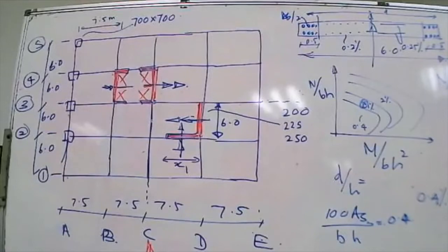They are useless calculations. Do a simple model where you will understand the exact behavior. And then if you want a very accurate result, allow it to a 3-dimensional computer program like ETABS. Because ETABS is written for buildings and it can take account of all these.